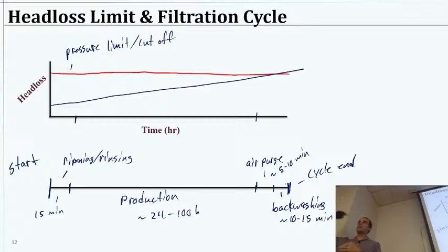It is an amount of pressure. If you stack up a very tall body of water, that's a lot of pressure it's exerting down just by the force of gravity, right? And so if you stack up more and more water on top of your filter, the gravity's causing the push through it, but it's going to be higher pressure the higher it gets.